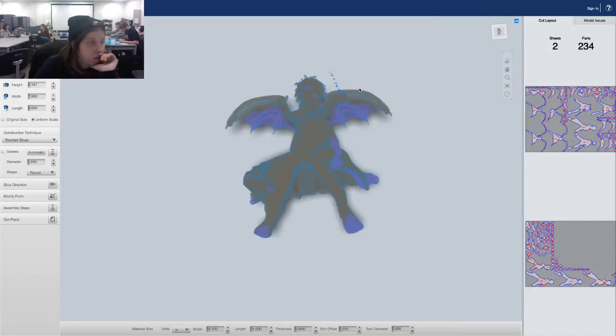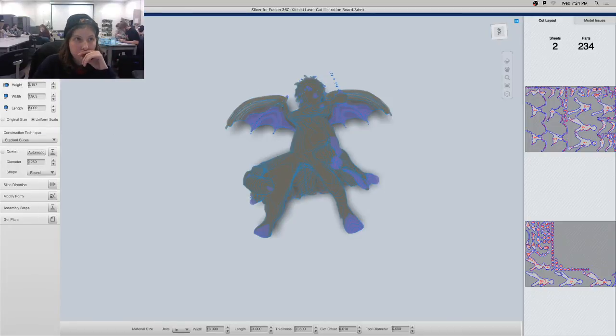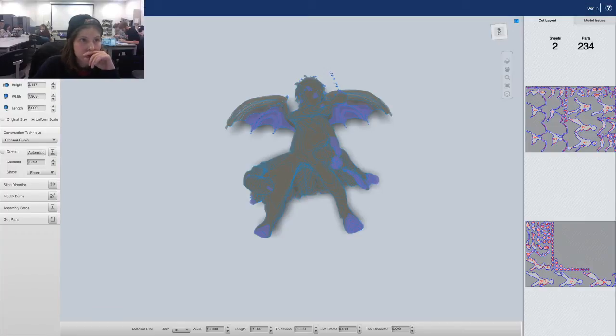Or you could also sketch the profile and then extrude into it as well. Yeah, we did that. So if you set up a sketch and then extrude the sketch, you can do a cut extrude into the body. Yeah, so do the same with the nose.